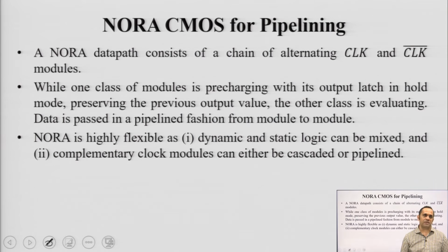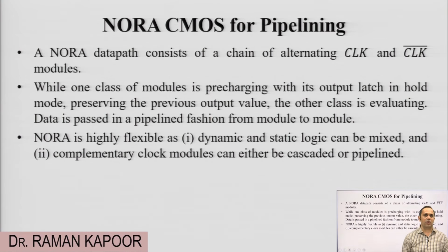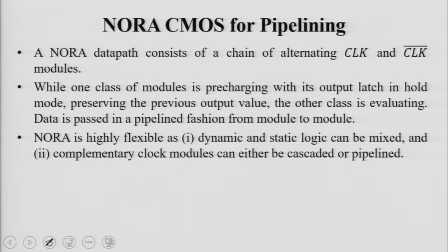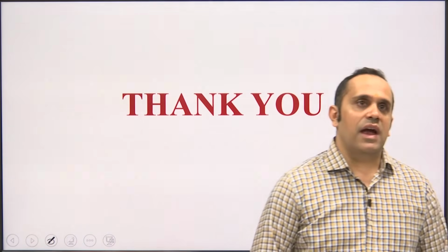It is highly flexible. So, in the combinational block, in the logic block, you can include both dynamic and static logic. So, it allows mixed logic design also, and complementary clock modules can either be cascaded or pipelined. So, if you only use the logic module only, you are working on a cascaded version, or otherwise you are working on a pipeline version. So, it allows you both. So, with this we end today's lecture.